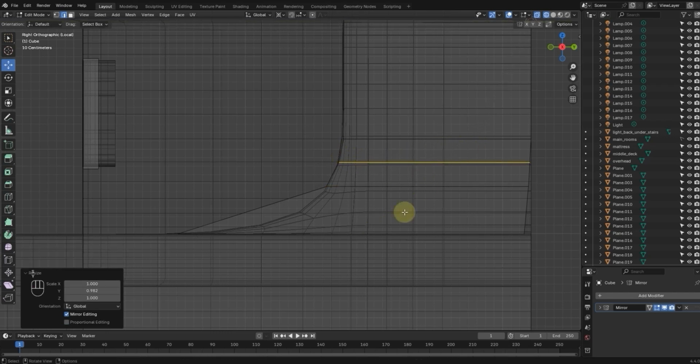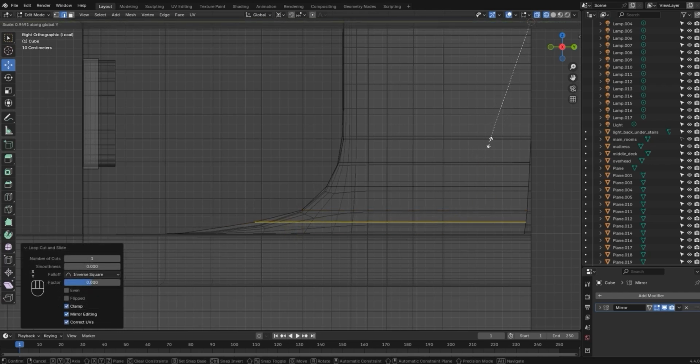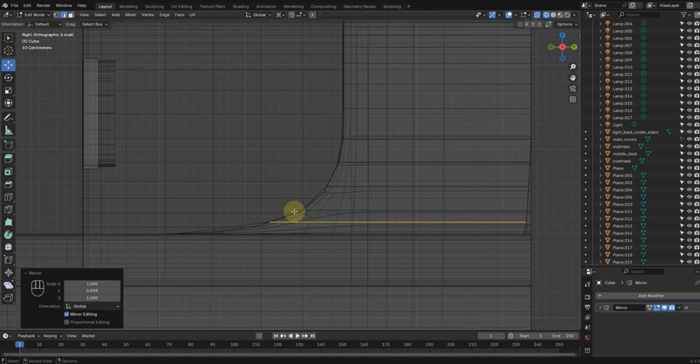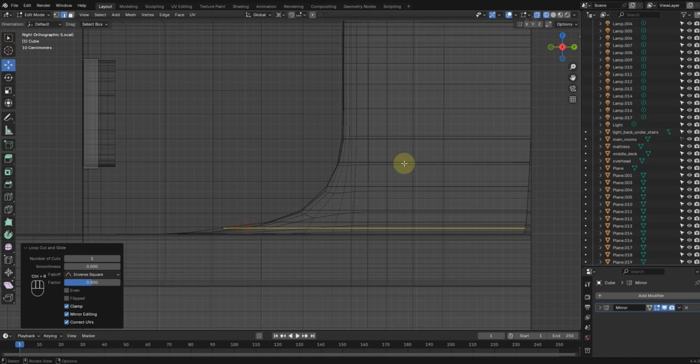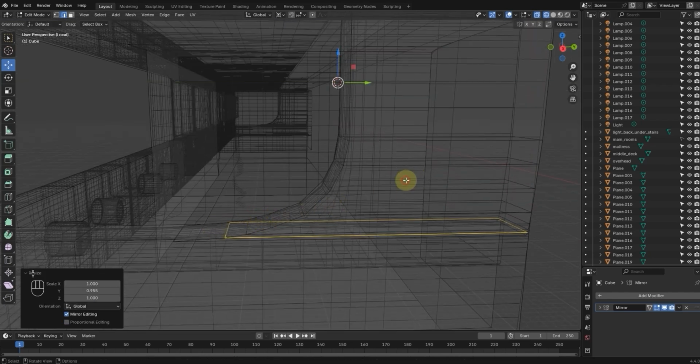I'll do the same thing just above it, just to make sure that it's aligned. Then below it, from center, I'll do the curvature again. Below that, I'll do, we still need one below that. So I'm basically selecting the layer, selecting the face, and pressing S Y to resize on the Y plane.